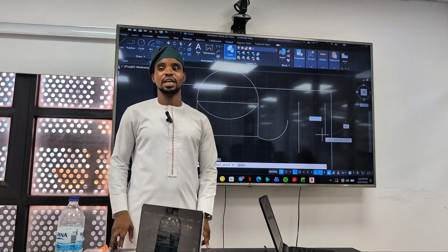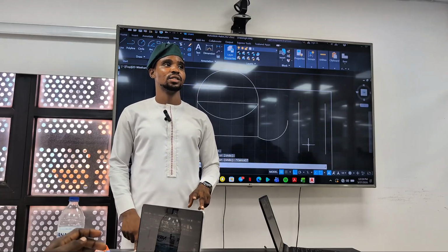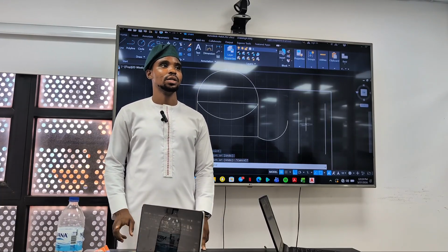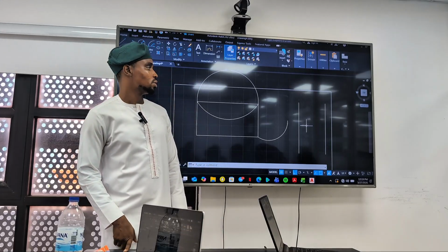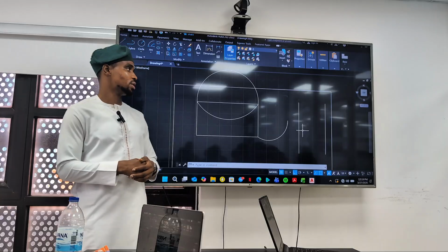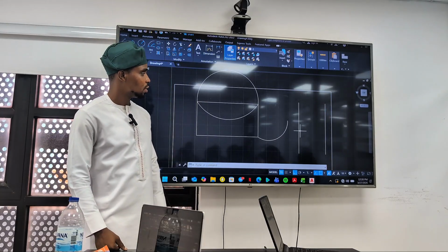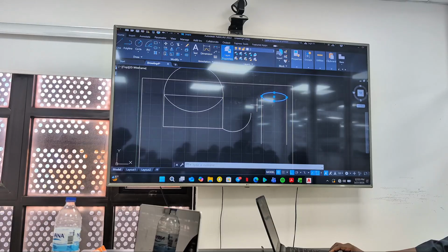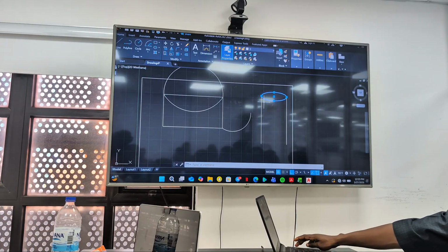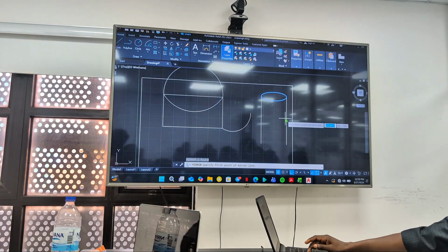So the command for line is actually L. I didn't tell you that. The command for line is L, and the command for polyline, I think, is PLINE, right? Yep. So there's no need of completing it to be LINE, just L, then enter. Right. So, okay. Now pick up. But because we still need it here, we're going to use it. M is the command for move. MI is the command for mirror.